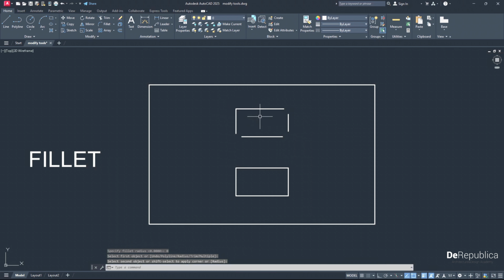To reactivate the previous command, we don't always need to click on the fillet command icon. Instead, simply hit spacebar on your keyboard to activate the previous command. Click, click. Again, spacebar, click, click, and again spacebar one more time. And so we have filleted, or closed, our shape.